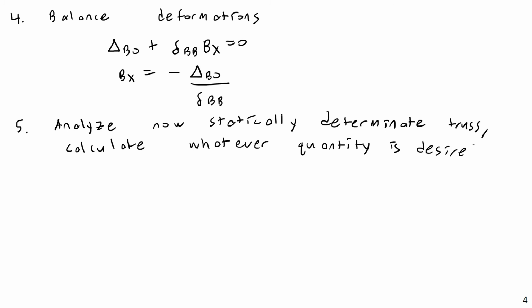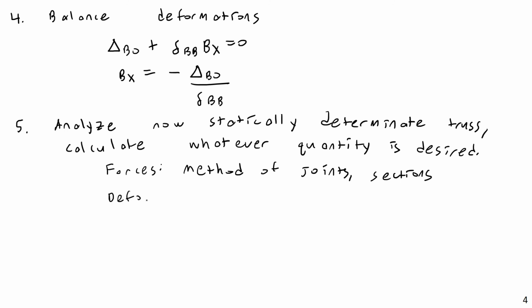So for example, if you're looking for forces, like internal forces in members, you could simply use method of joints or method of sections from statics. And if you're looking for deformations, displacements, or rotations, here you could use virtual work again.